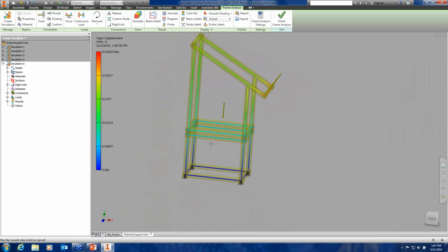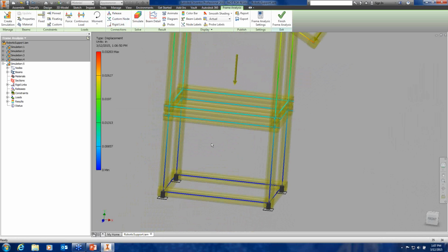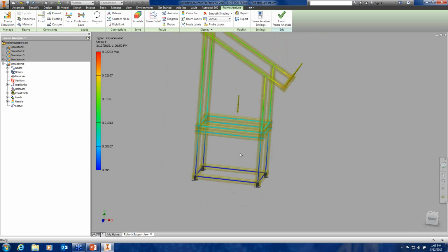And notice how it passes right on through to the other assembly. Okay? So even though that was a separate assembly, where we actually did an analysis on it earlier at a fixed point, it does understand that in this particular mode, in this particular assembly file, they are attached together, and so those stresses are passed right on down. And so you can see what's happening here is the stresses are starting to affect our lower assembly as well.